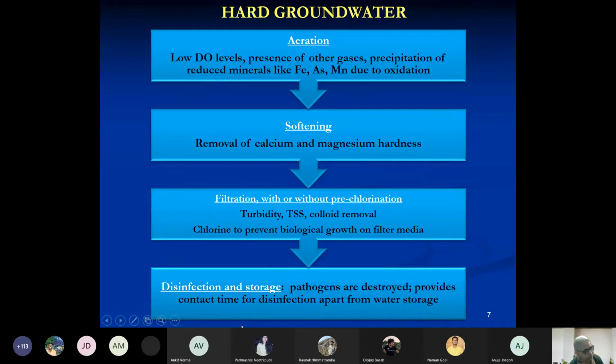So if it is the end of the water treatment plant, most people, maybe 99%, I don't know, are using chlorine. You can also use UV radiation in your home treatment units. Almost all water treatment units that are what we call end of pipe or point of use treatment units are all based on UV radiation.